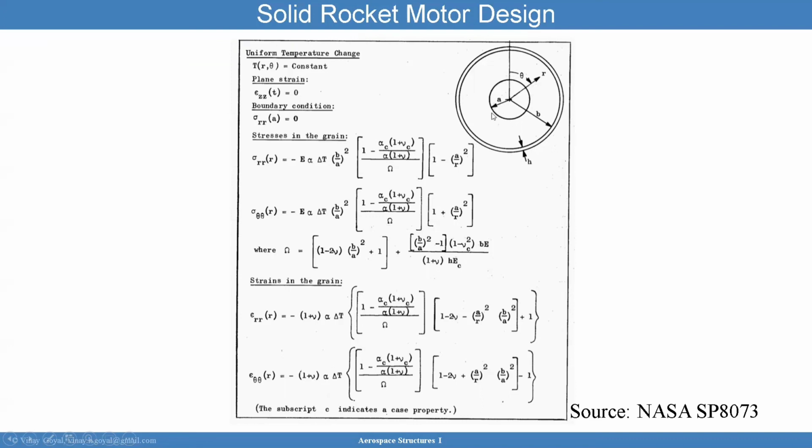And A is a bore diameter, B is a radius to the inner portion of that case. So all that information is given very well. So these are straightforward calculations. And the important thing to remember is we don't want to have a failure due to stresses being too high during storage. Some of these rockets can be stored over 10 years, as an example.